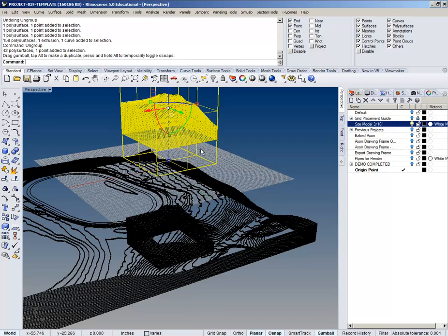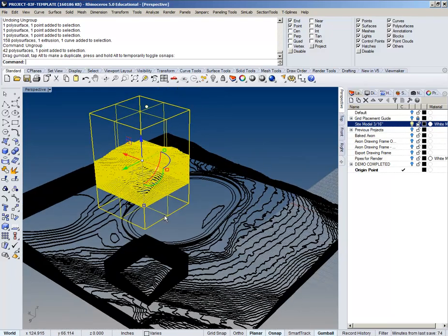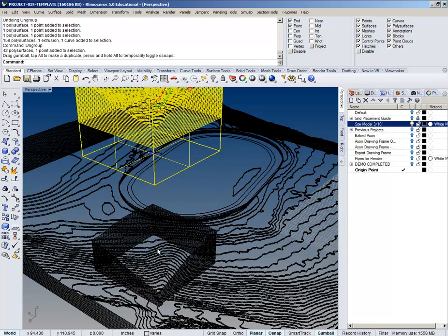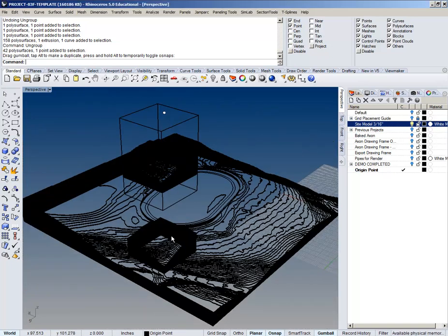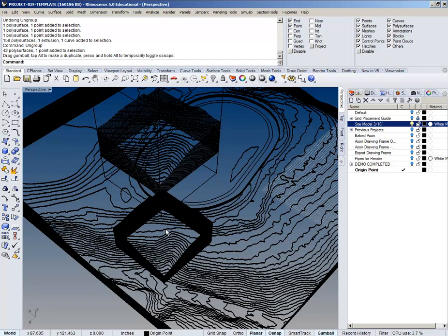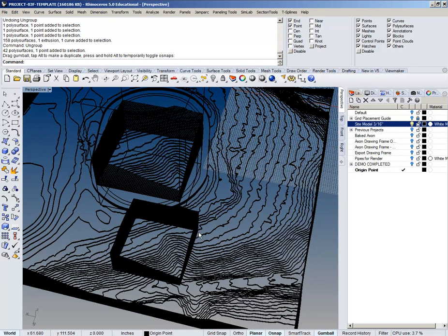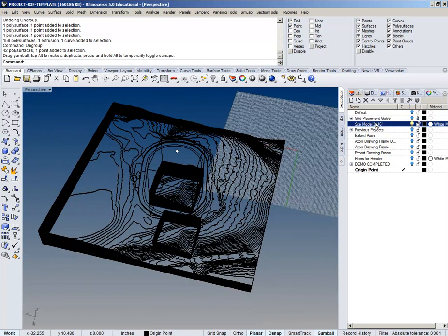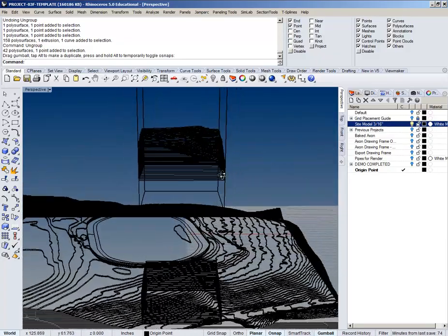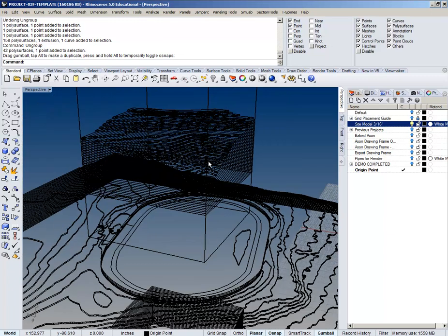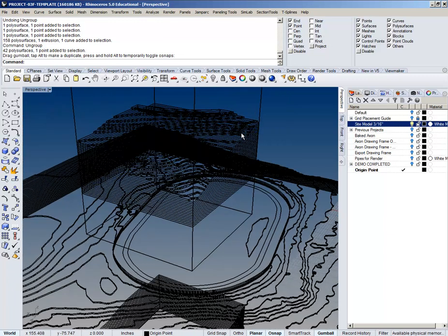Again, if you don't like working all in the same place there, right, this keeps all that split stuff as well. Not going to hurt anything, it's a little bit of extra geometry. If you're not happy with it, you can just duplicate this whole layer and run that on there and then delete everything else. But here you've got a nice piece of the site as well that you can use as a reference for a topo model.